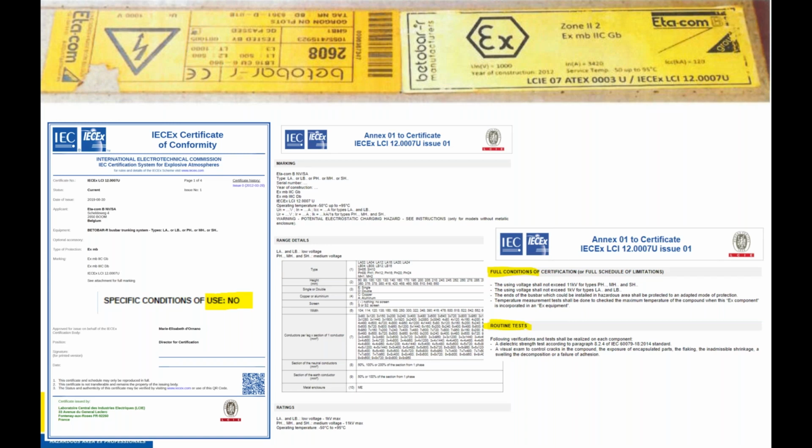identical to the manufacturer's IOMs. If you are referring to the standard for all clause references, you are not following the order of precedence with EX documentation. If you don't have the certificate on you, you are not doing the inspection correctly. It is invalid. Your inspection is completely and utterly invalid without knowing the conditions of use.